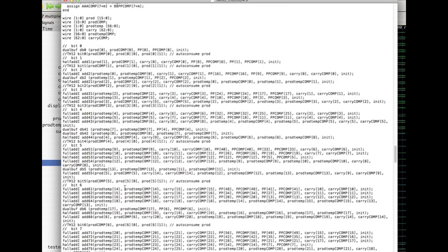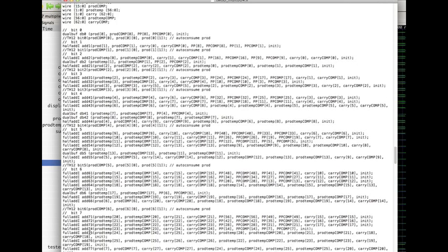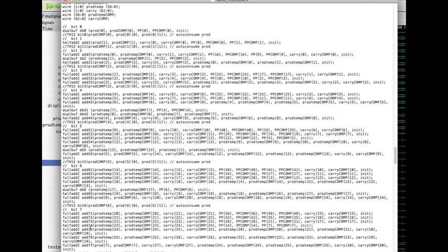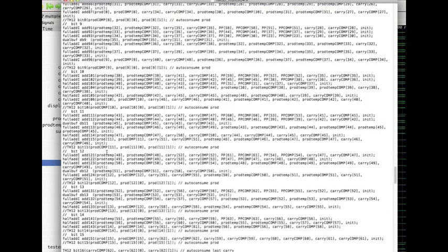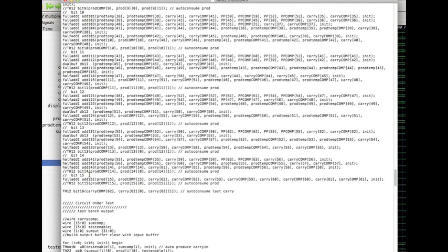And these are the adder trees, right? This is the tree for bit 0, the tree for bit 1, bit 2, bit 3, bit 4, bit 5, bit 6. And you can see they get a little bigger as we go up towards the diagonal. And they're all built out of full adds and half adds to generate the carries. So we get bit 7, then we go through to bit 15, which is a small tree again. So let's look at the signals now.